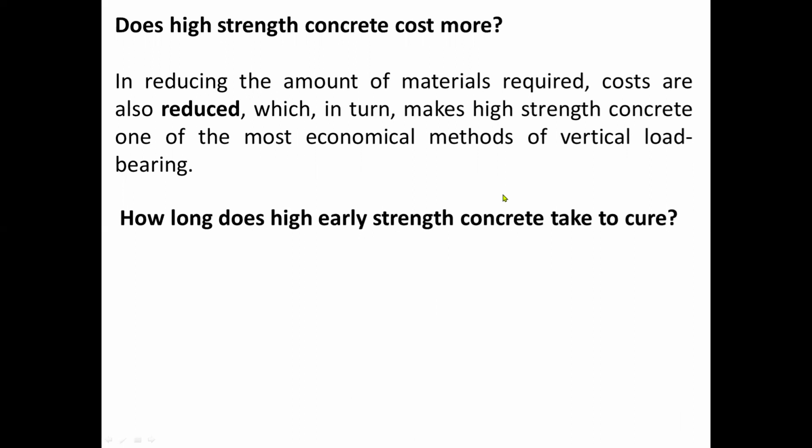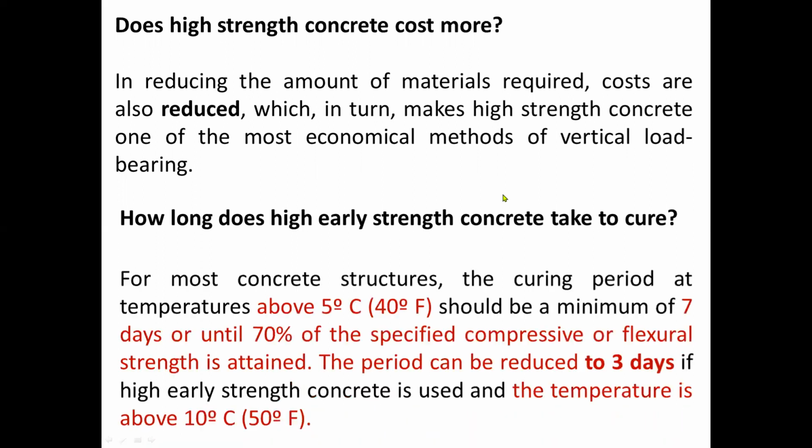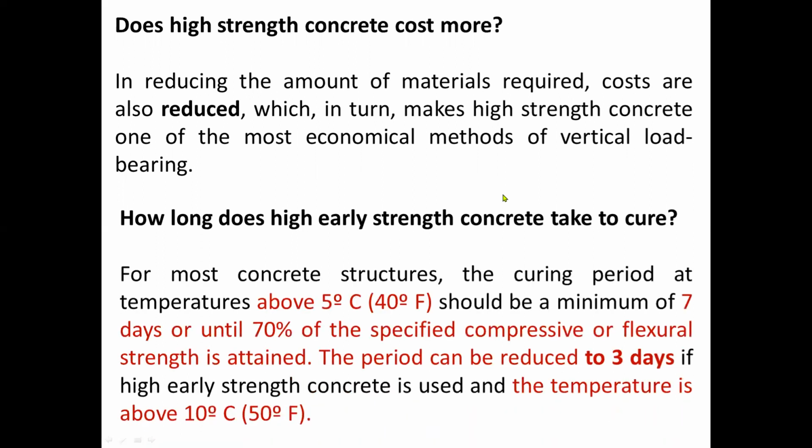How long does high early strength concrete take to cure? For most concrete structures, the curing period at temperature of above 5 degrees Celsius or 40 degrees Fahrenheit should be a minimum of 7 days or until 70% of the specified compressive or flexural strength is attained.